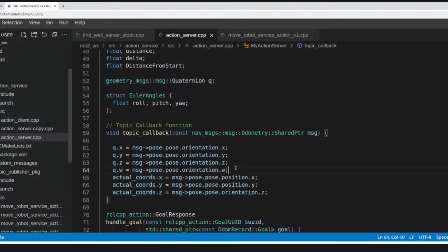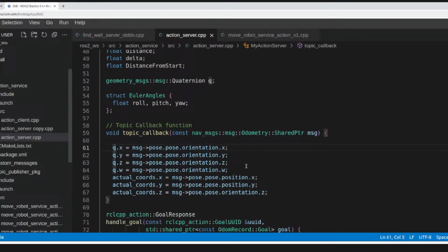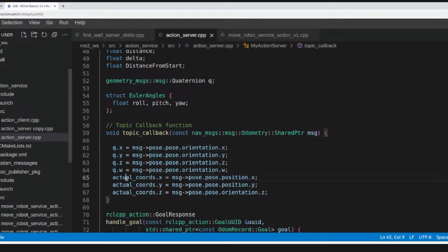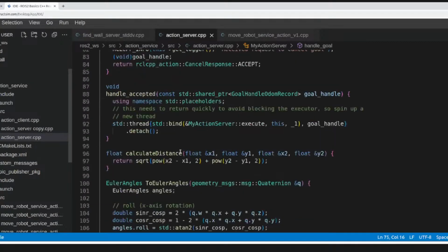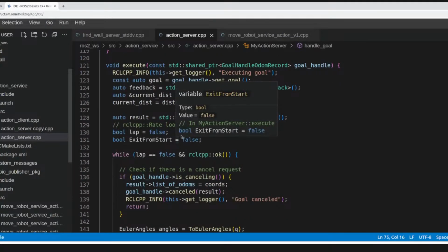Right now in the odometry callback, I'm creating a quaternion message just to store all the quaternions, because I'm receiving quaternions from the odometry, and I have to convert to Euler angles to calculate the yaw. And then I'm calculating my actual coordinates. This coordinate z is not correct because it's getting just the quaternion. It should get yaw, but I'm going to transform that later. The important ones are x and y in reality, because it's the graph of the path that we're interested in.